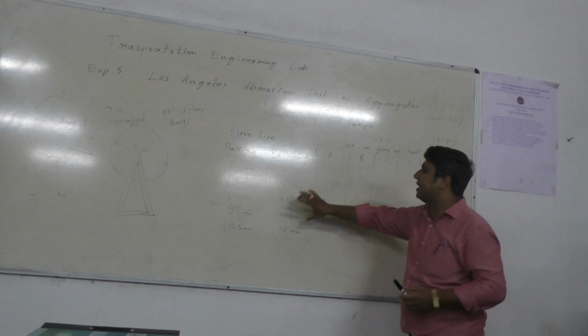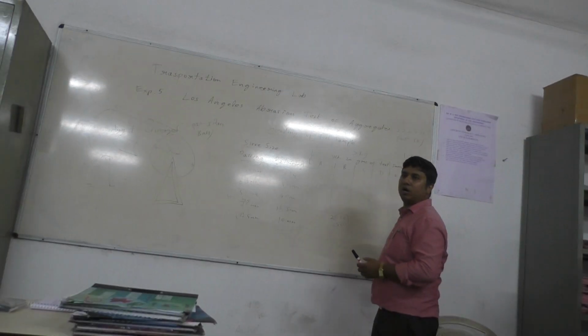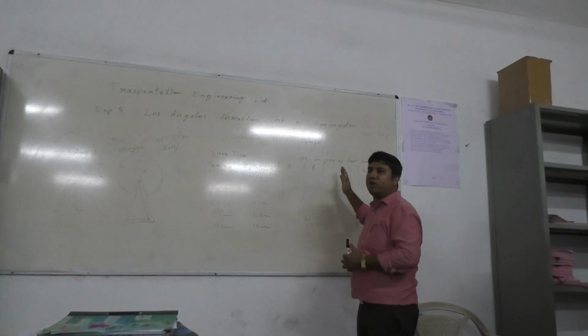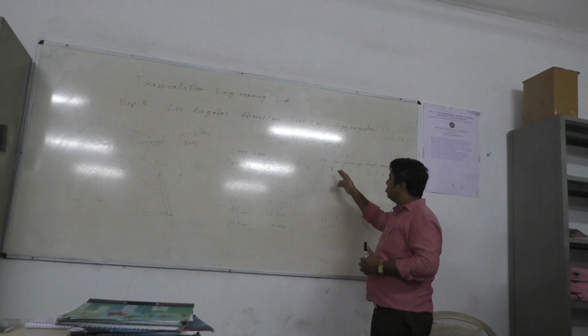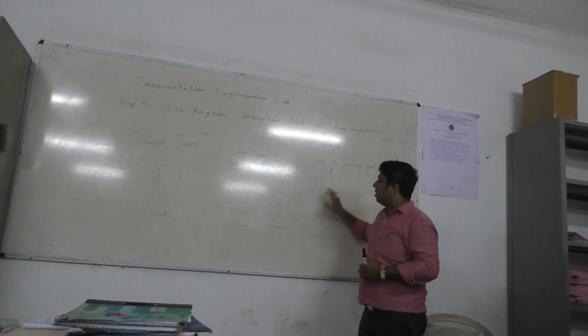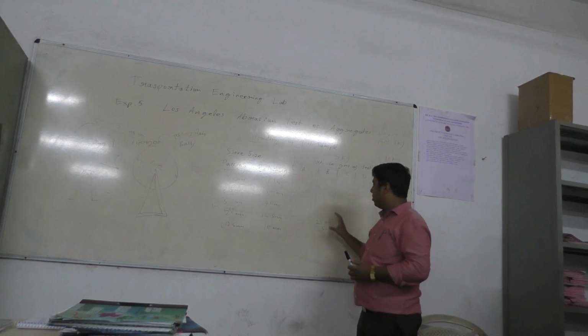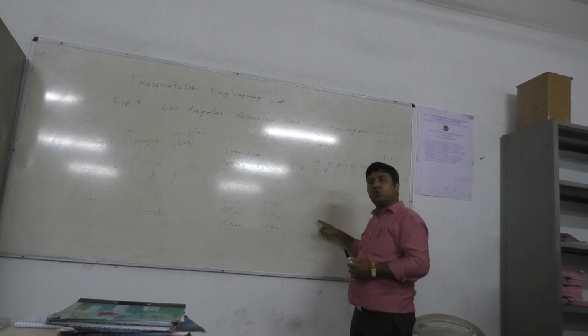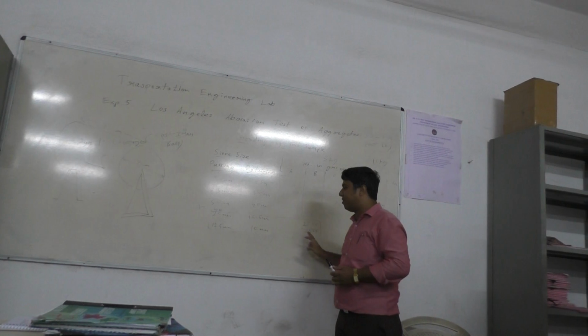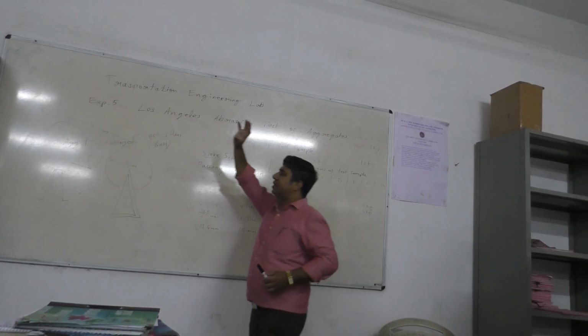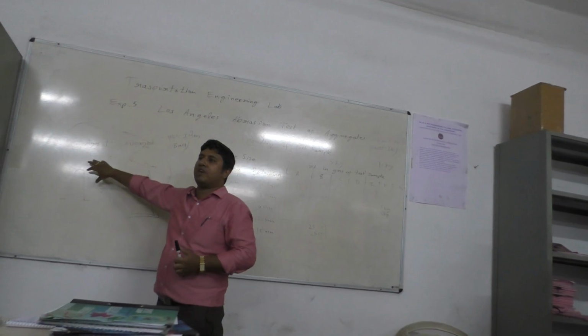For different sizes of aggregate, we have different gradations. So this range of aggregate falls under grade B. For this, we have to choose 2.5 kg of this range of sample and 2.5 kg of the other range. Then the 5 kg of sample we will put together into the machine along with the 11 abrasive charges.